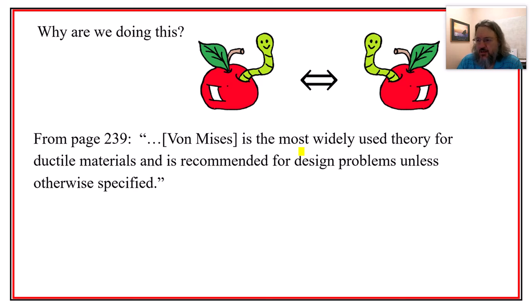Now, if you use finite element analysis, you'll know often if you hit solve and it pops up with the results, that's von Mises stress. And why would we use that? Well, for one thing, it's always a positive number. We don't have tension or compression in von Mises. Why? Because it's comparing itself to the pull test, to the place that we got the strength data.